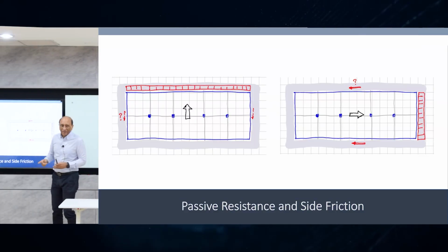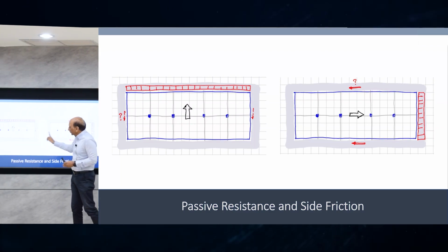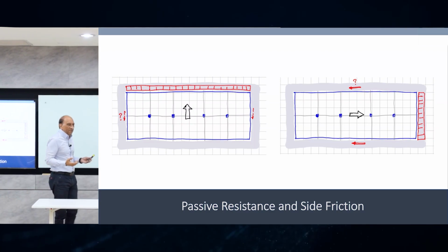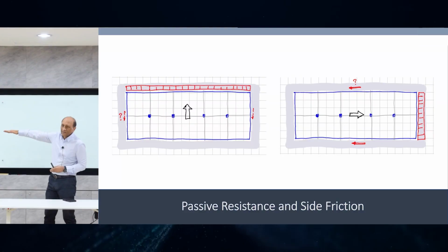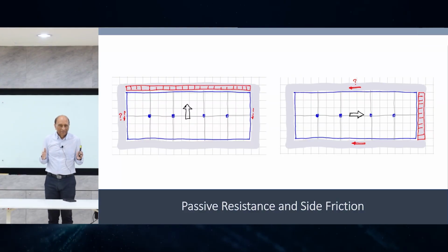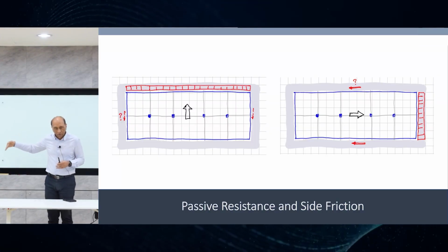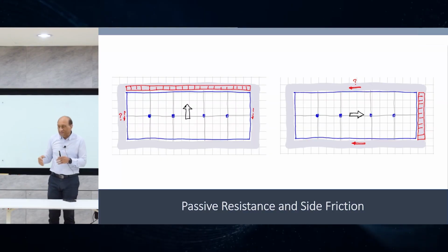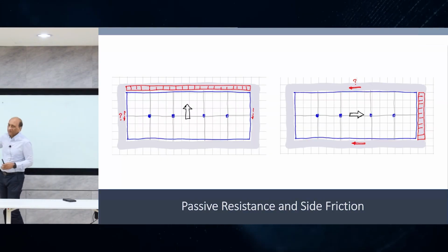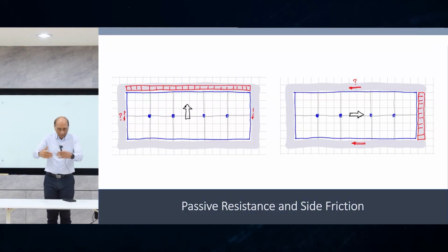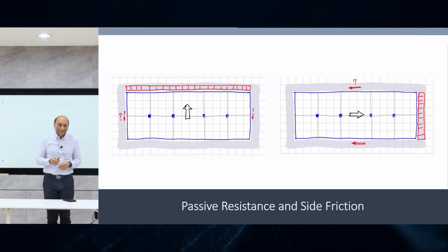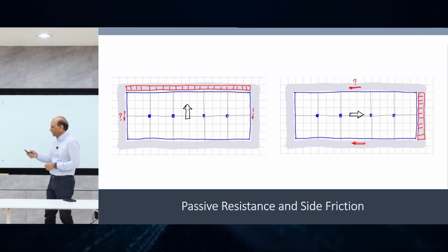But the situation is very different when the same force is pushing on the longer side. Earthquake force is the same in each direction. So when you do that, the whole building will immediately hit that one, because the side walls are small. The friction will not develop. So then you have the pressure developing on those long walls immediately. So this geometry, the shape, the length, and other things will govern a lot what kind of pressures are generated on the wall and also on the soil on those sides. Okay? Very different behavior. But things get more complicated, or rather, more interesting.